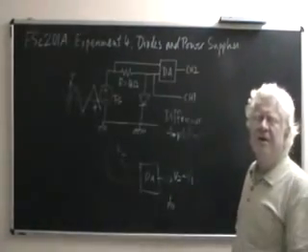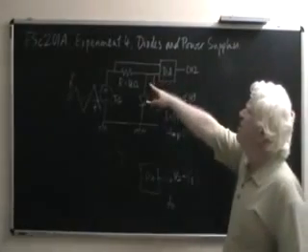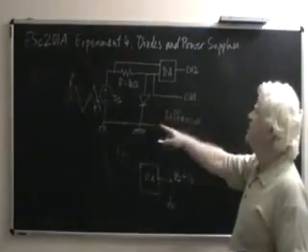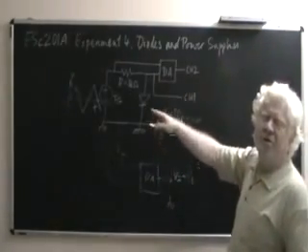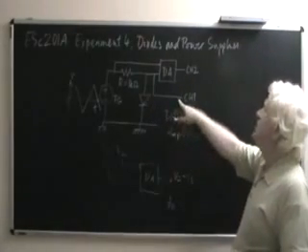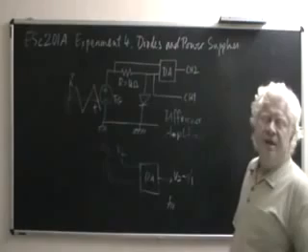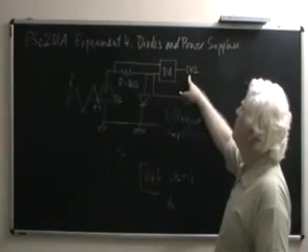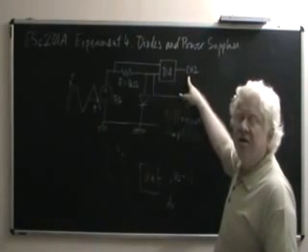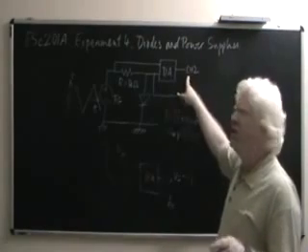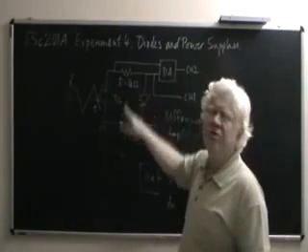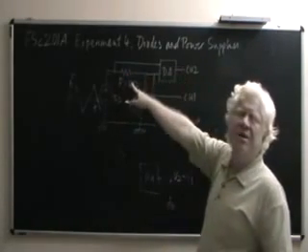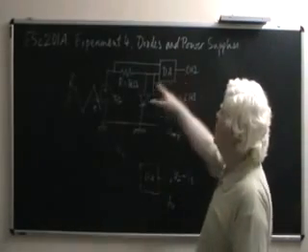That is possible, but if we did that, just the measurement of the current or the voltage proportional to the current would consume both the channels, and we would require a third channel, which means a new scope altogether, because this scope has only two channels, to measure the voltage of the diode. Thus, to save on oscilloscopes, we use a difference amplifier, and the difference amplifier gives you an output proportional to the current. To work out the constant of proportionality, look at this resistor. This resistor we have used is 1 kilo ohm. So if it gives you 1 volt here, that means the current is 1 milliampere. If it is n volts, it is n milliamperes.